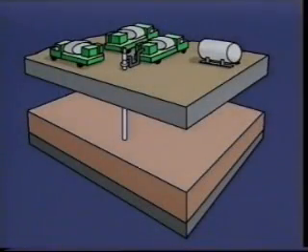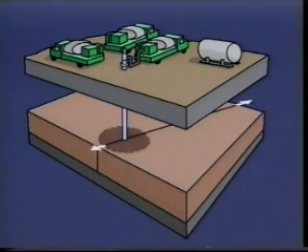Fracture stimulation using acid has been successfully employed on low permeability carbonate reservoirs and occasionally on sandstone reservoirs with extensive deep damage. This type of treatment results in acid penetrating hundreds of feet into the reservoir through a hydraulically created fracture. The fracture maintains excellent conductivity as a result of the acid etching flow channels deep into the formation and/or removing sufficient non-recurring damage to allow fluid to flow. The uneven etching pattern on the fracture walls prevents the fracture from healing after the treatment.